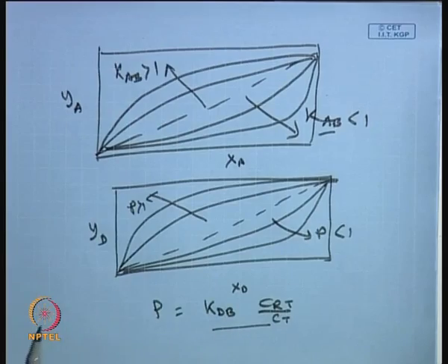Okay. Now, using the equilibrium curves, one can really go for the ion movement theory and evaluate what is the ion velocity in the ion exchange resin. Once you know the ion velocity in the ion exchange resin, exactly like the chromatographic column calculations, we can find out what is the total residence time, the total regeneration time, the total washing time and the total cycle time. Okay. So, in the next class, we will explain the ion movement theory and we will solve one particular example to calculate the total time that you will require for a full ion exchange resin cycle.